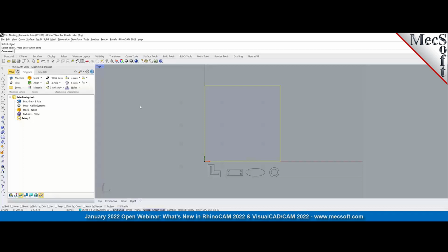Also, now that we're posting the G code whenever we generate an operation, you can use that in combination with the suppressing rules, where if you're working through a part and you're finalizing your operations, as you go down through the machining job, you can suppress those operations that you in your mind are complete and you don't want them overwritten when you regenerate. Right. And you can use that in combination. That would be a big time saver as well.